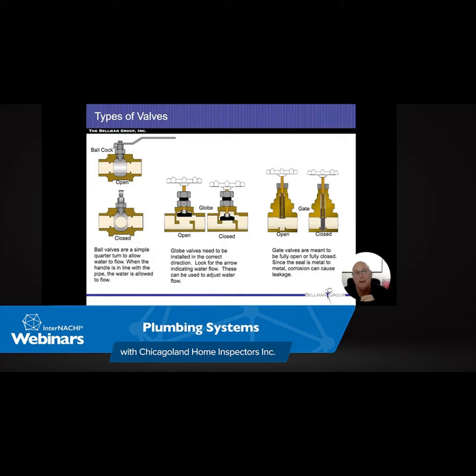What I would like to encourage you to do is spin that pressure relief valve. If it spins easily, chances are it's not corroded. If you have to give it some pressure and then it spins easily, it's corroded in there. If you can't spin it at all and it's so tight in there, it's corroded in there. If it's corroded, it may not open when we need it to open. And that spring in itself is going to hold it at 150 psi.